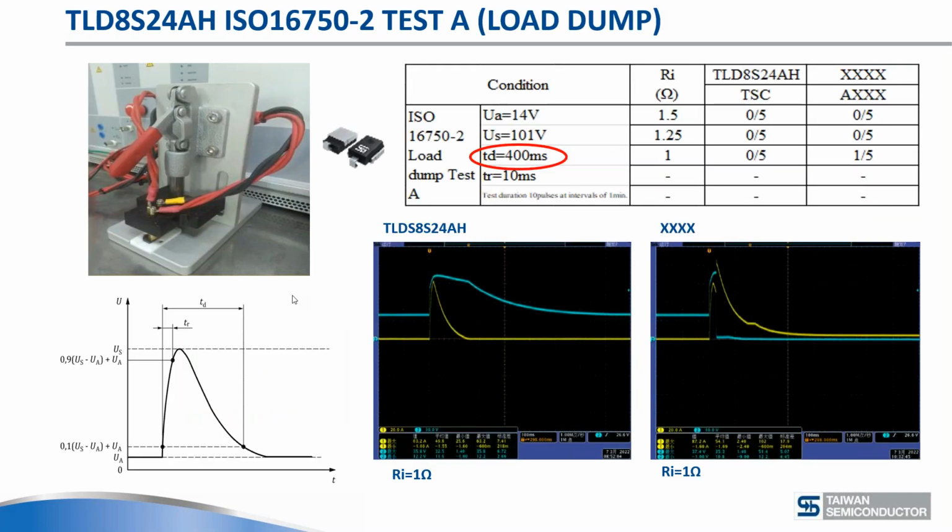Next subject is automotive pulses, and I circled it in red at 400 milliseconds because it is a little bit more complex, right? We mentioned that the shorter pulses, 820 to 1000, are predominantly die driven, and of course how the die is attached, with a good solder joint, no solder voids or anything like that. Then you'll have very good performance. If you go to 400 milliseconds, obviously the heat spreads through the package, but it doesn't spread so much that the PCB becomes the dominating factor, like in the steady state environment. So it's really complex, somewhere in the middle.